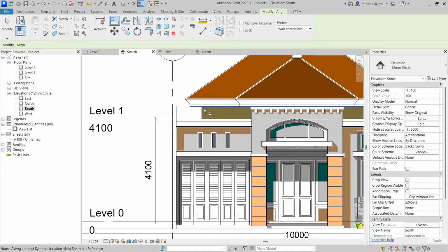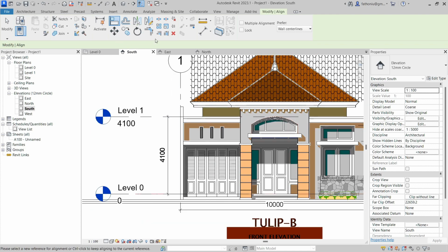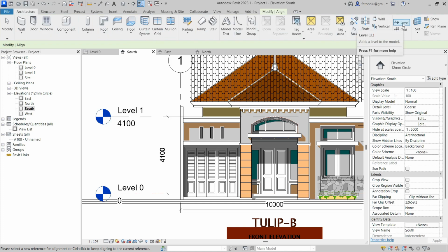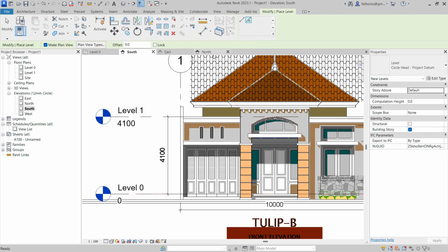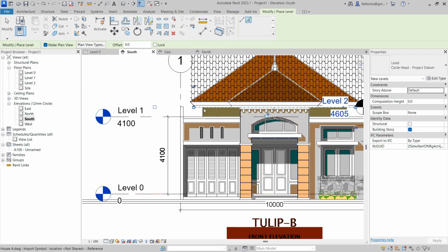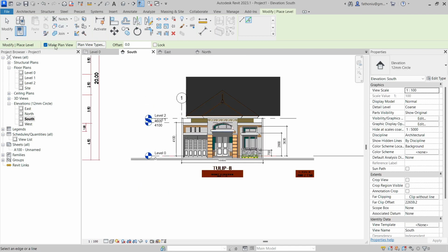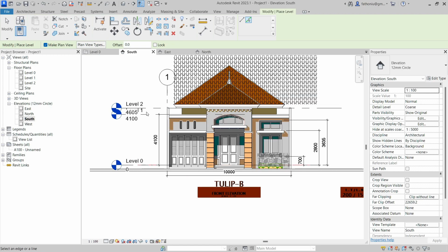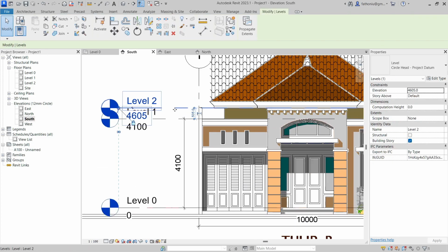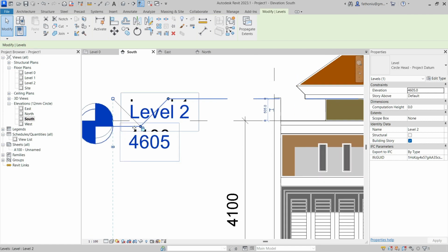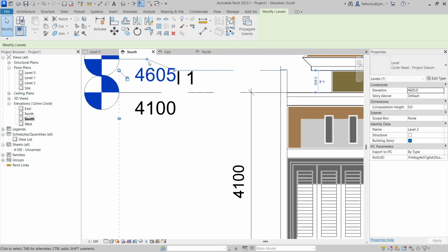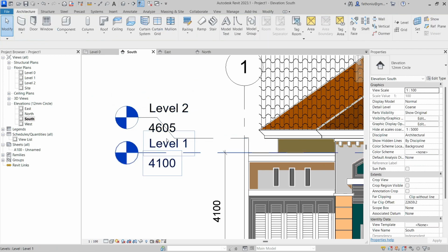The garage, we have another wall here, so we need an elevation. So we go to architecture, we have level here, and let me pick the line and use this one as level. You can see here on the top we have make plan view. So when we create a new level, the floor plan is also automatically created. It will copy the grid line from the bottom. You can see here it is too close to each other, so I bend it up toward that so you can have it clear.